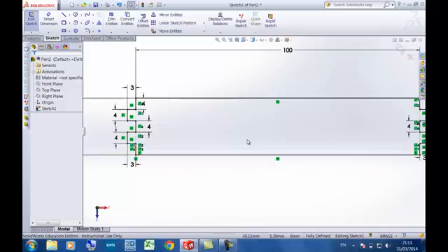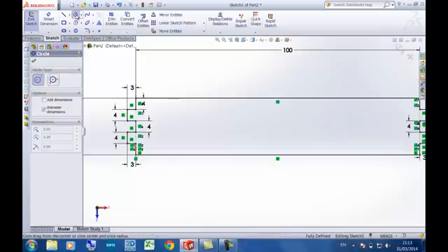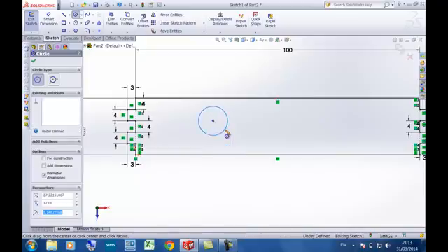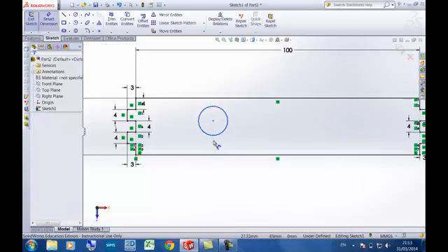Okay, so what we're going to do now is find another drawing tool. It's called circle. Click on this, and we can draw anywhere for now. We're going to draw over here. It doesn't really matter, because we can use our smart dimension to decide how to actually put down what we want. So draw a shape on that rectangle.